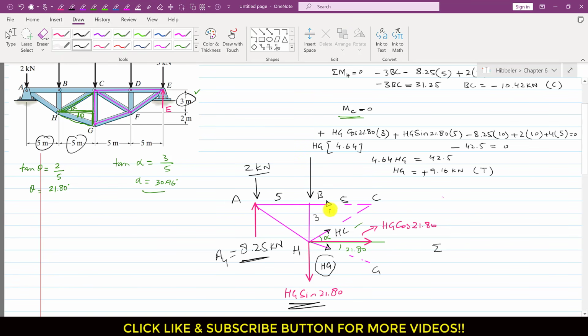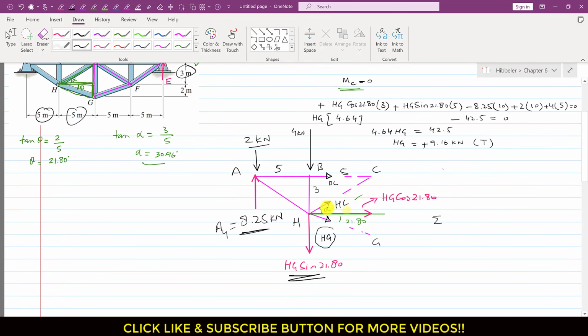So this is that BC, this is that 4 kilonewton force, right? So now I need to eliminate this HG and this BC from our equation, right? So if I extend the line of action of this HG like this, and if I extend the line of action of this BC, they will intersect somewhere, and let's say that this intersection point is O, right?